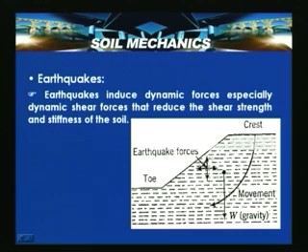So this is the toe, and this is the crest, and this is the movement which is initiated because of the earthquake forces. So earthquakes induce dynamic forces, especially dynamic shear forces, that reduce the shear strength and stiffness of the soil, which actually causes a slope failure.